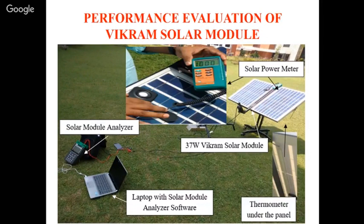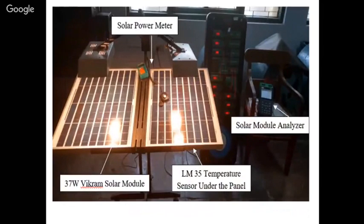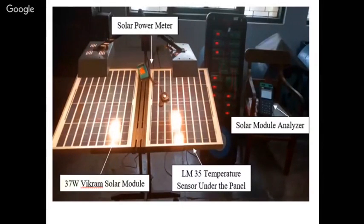So we found the efficiency outside, and again we did the same experimentation inside the laboratory. With the solar power meter, we found the irradiation, because we took readings at around 10 places here and 10 places there, and took the average. That average gives you the total irradiation falling on the panel.